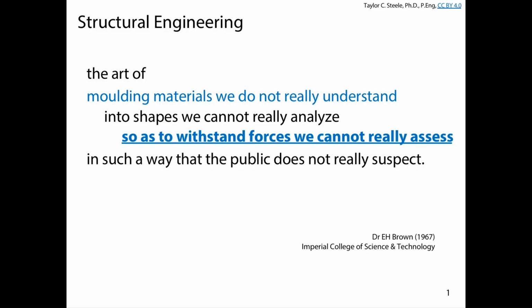So we did dead and live loads, snow loads, and one of the key aspects of how we treat those loads is, for the most part, we assume that they act more or less uniformly over the floor area, right? That makes the math for us very simple. It's not exactly right, but it's adequate for the purposes of performing the structural analysis we need to perform, and eventually to select some members to resist those forces.